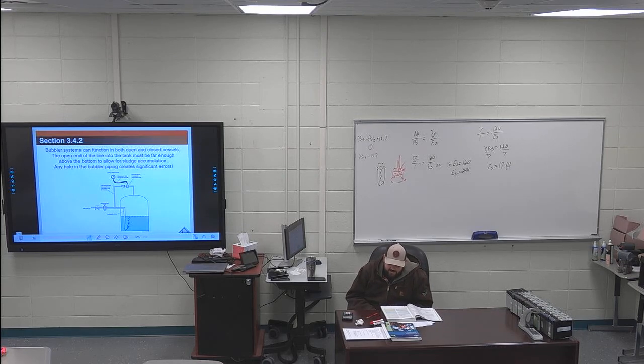On closed tank installations, the line connecting the differential pressure transmitter to the top of the tank is called a dry leg. It is used for installations in which the process vapors inside the tank are non-corrosive or non-plugging and are unlikely to condense in the line.